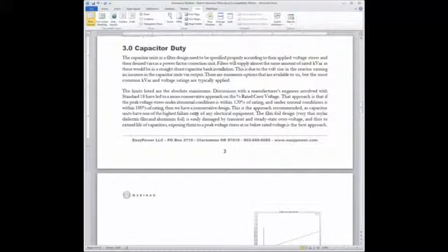The capacitor is typically created by thin mylar, dielectric, or paper. And it's very thin, again. If it's mylar, it's typically impregnated with oil. And I'm speaking mostly about medium voltage capacitors. Since it's so thin, its main mode of failure is dielectric failure. To make sure we cover for that, we take the rated voltage of the capacitor for whichever one we've selected, and we could do a square root of 2 factor and start adding up all the peak voltages, but you can do it in RMS too. It's kind of the same thing.